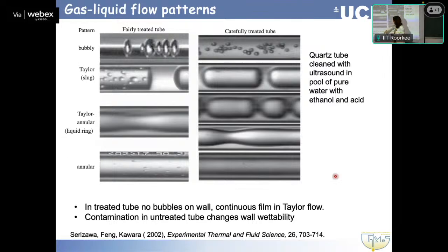of the map. And then annular flow, you can't really see it very easily here, but there is a film and the main core annulus. And there is a dispersed flow that perhaps from visual observations, we cannot see much. And what I wanted to now show you is that there are a lot of references here. It's worth checking them. A lot of things play a role on what flow patterns will form